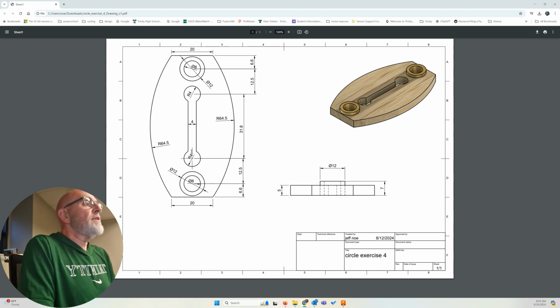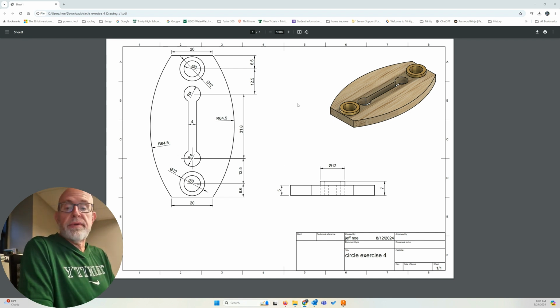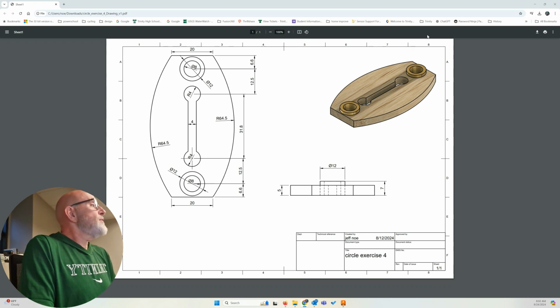Trim away the excess. That'll give me that portion of the shape. And notice that does not get extruded. So I should be done with my sketch at that point. I'll extrude this section 5 millimeters. That'll be one body. I'll extrude these two as new bodies because I'm going to give those a different appearance. Let's get started.